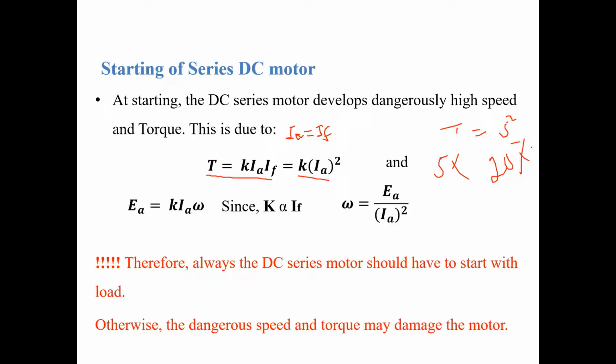Always when you start it, be sure that you have connected a heavy load, a rated load, to the shaft. Otherwise, the dangerous torque and the dangerous speed at starting will damage the motor itself. So it's very dangerous.